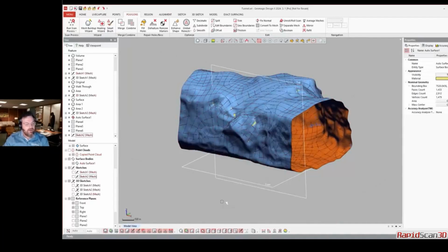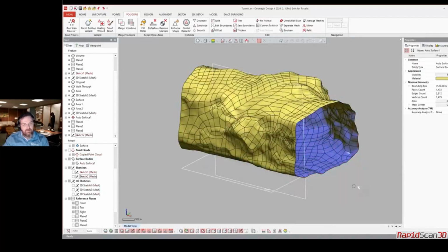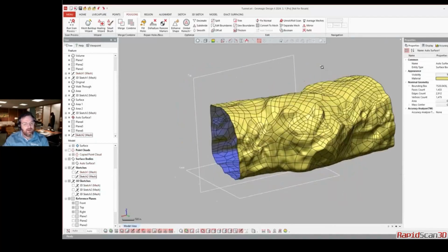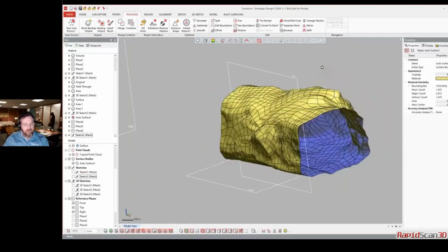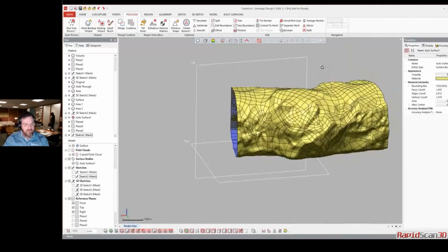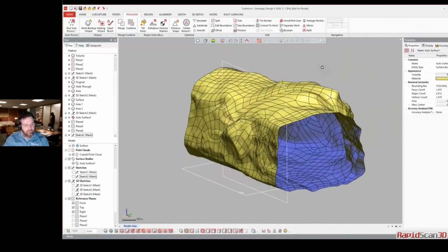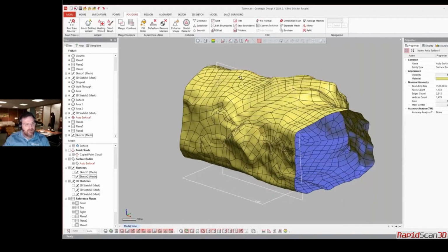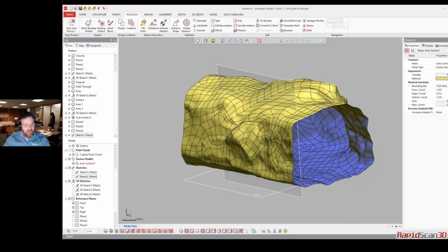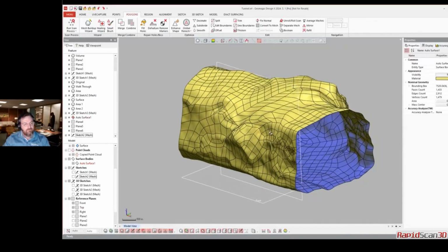Here we took that mesh, and I'll hide the mesh there, and we ran it through our auto surfacer. You could have done this for the entire thing, but I was just taking a certain section of that and creating a NURB surface from that, and saving that out as a STEP, IGES, neutral, all those different types of CAD formats.